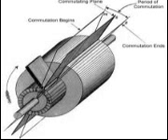The voltage induced necessitates the use of material for brushes which has a definite contact resistance. Also, this material must be such that the friction between the commutator and the brush is low, to prevent excessive wear. For these reasons, the material commonly used for brushes is high-grade carbon. The carbon must be soft enough to prevent undue wear of the commutator and yet hard enough. Outer rings for insulation. Figure 9-14. Commutator with portion removed to show construction.